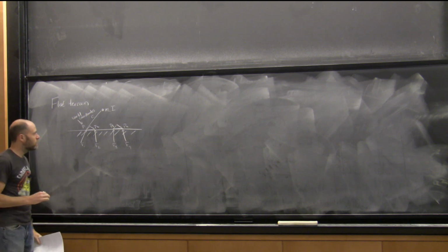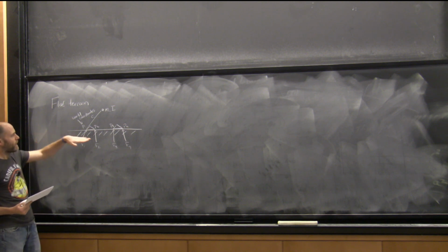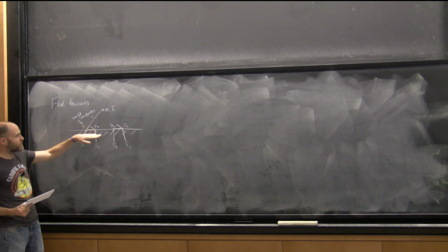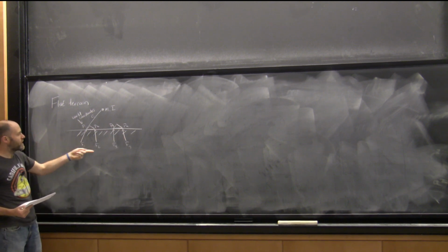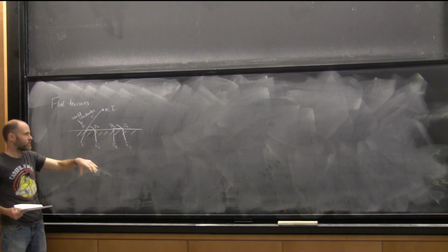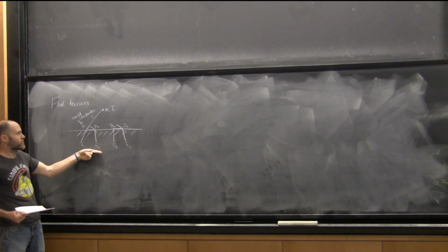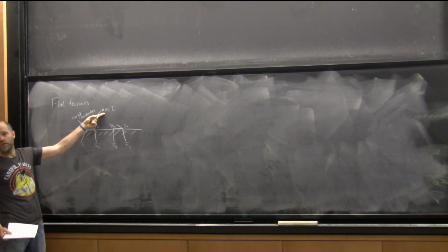Then, what's interesting to understand quickly is that in this special case where I've got feet on the ground, constraints on the forces like friction or no suction, so a unilateral constraint, quickly impose limits on what I can actually do moving around my center of mass.